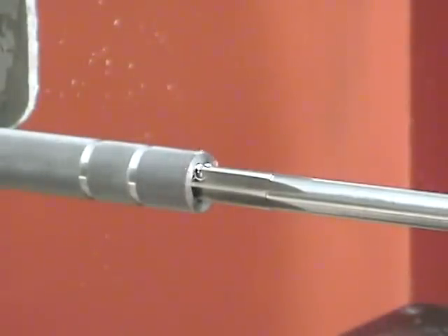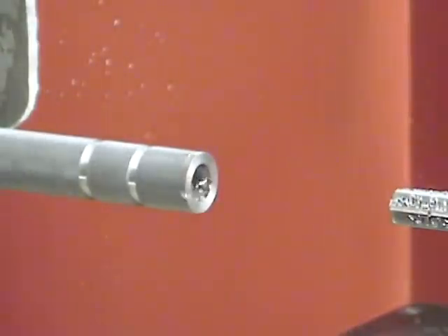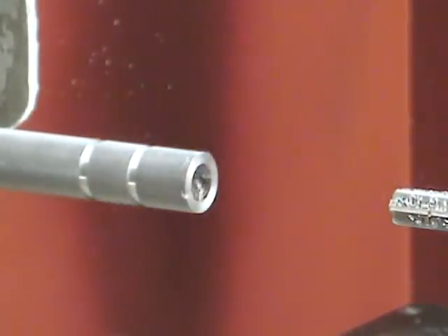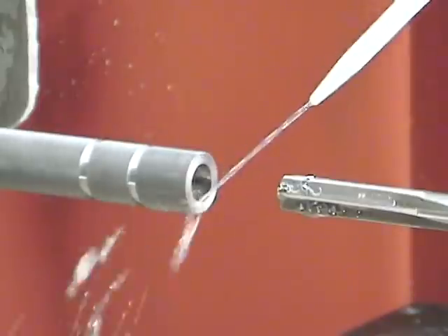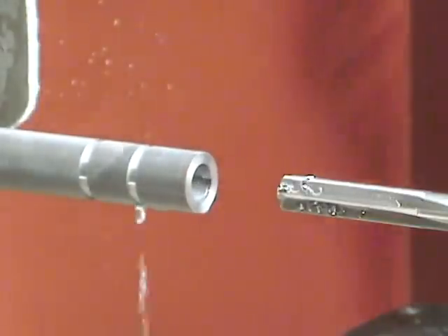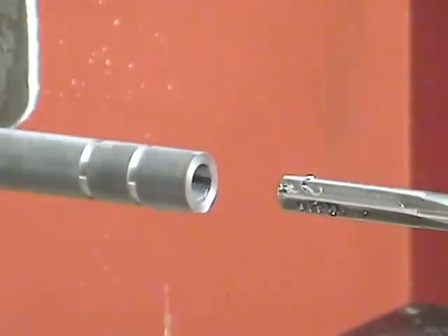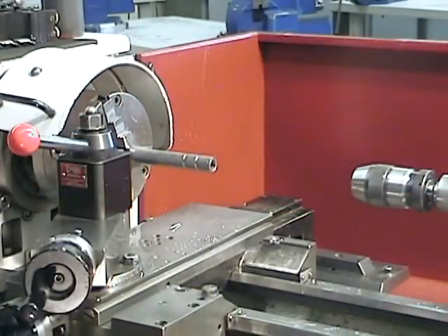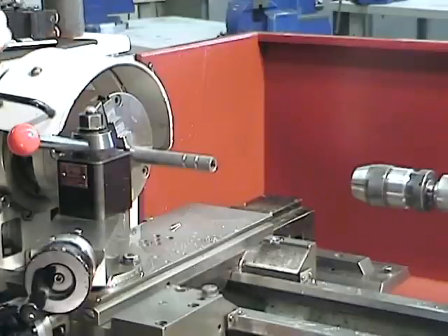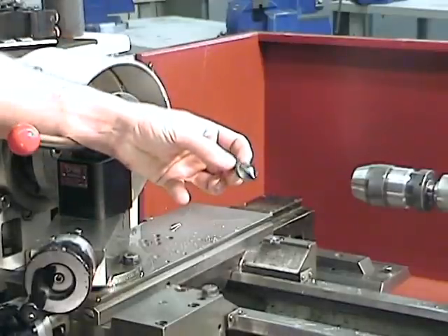And that means that I should have increased my chip load by quite a bit, which isn't a good thing. However, this tool has 6 cutting lips, and that means that my chip load remains about the same in both cases. Note also that in this case I'm retracting the tool rapidly rather than stopping the machine before retraction. I can do that because this hole is quite shallow. If the reamed hole is quite deep, really I recommend stopping the machine first.